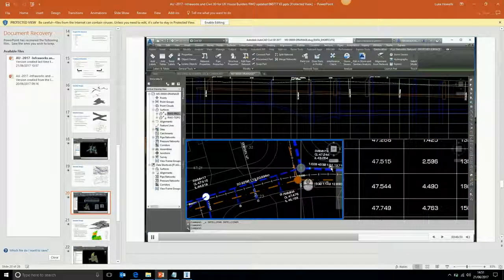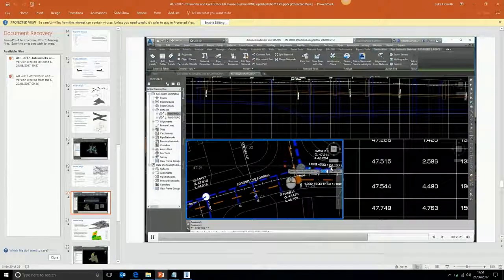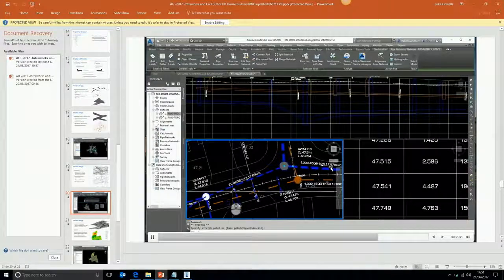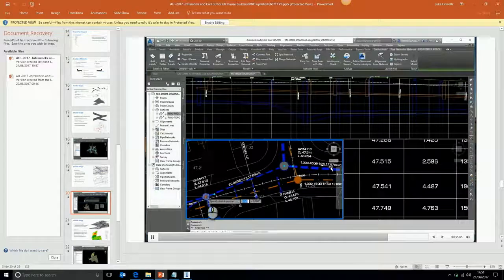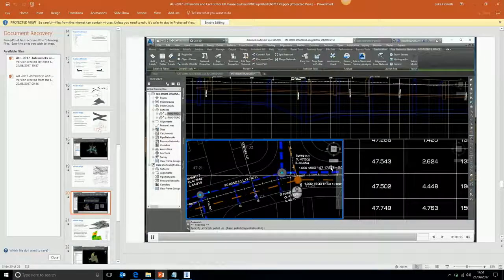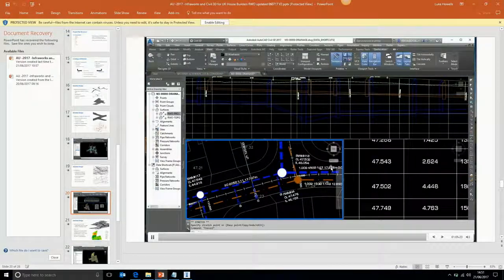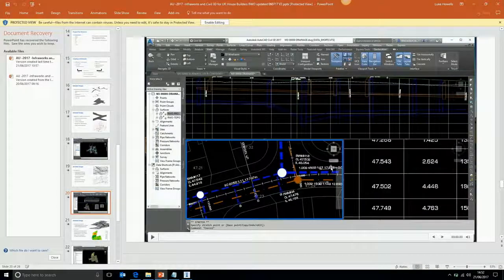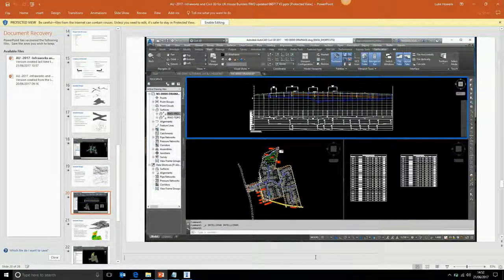We're going to drag this manhole ever so slightly. There might be a constraint within the road, there might be some services that you want to avoid. And as you can see on your profile and in the manhole schedule, everything's updating. So the drainage is fully dynamic, and this removes the human error that most engineers typically encounter working on large residential or commercial industrial developments. And I'm going to hand you back over to Craig to talk about the composite M3 surface.